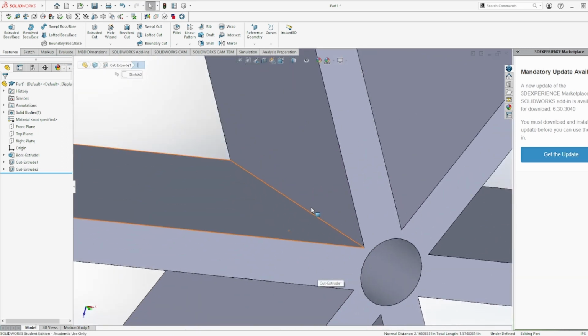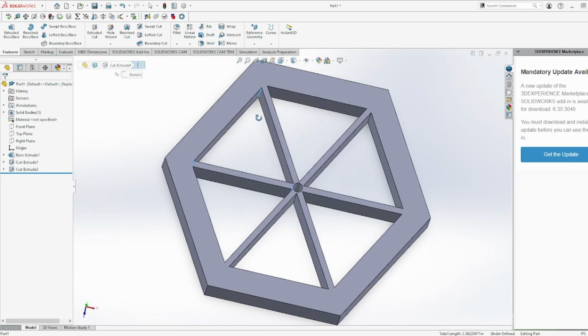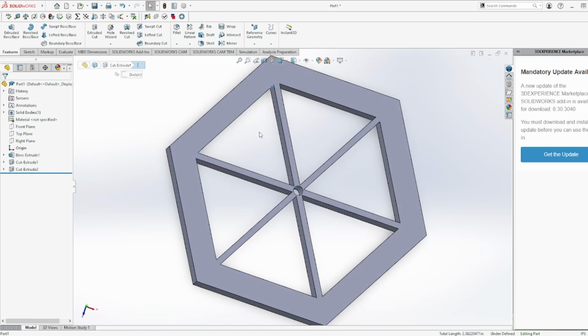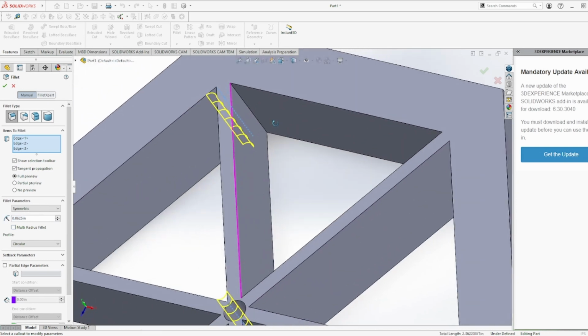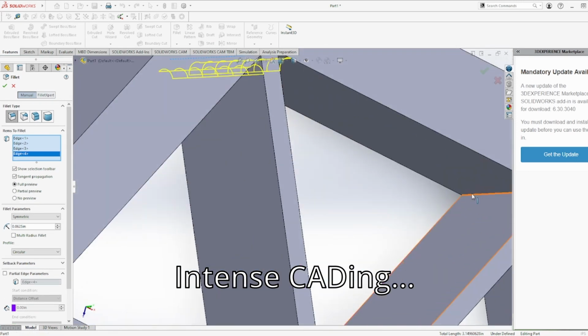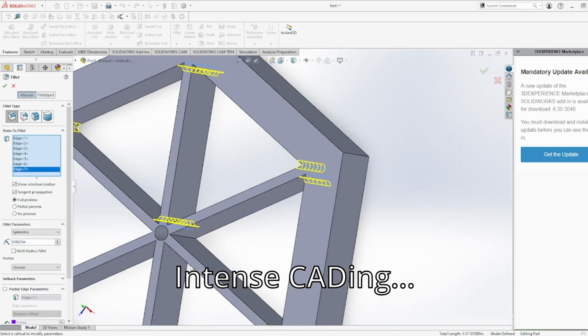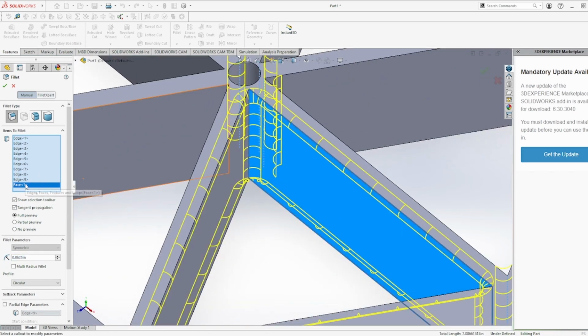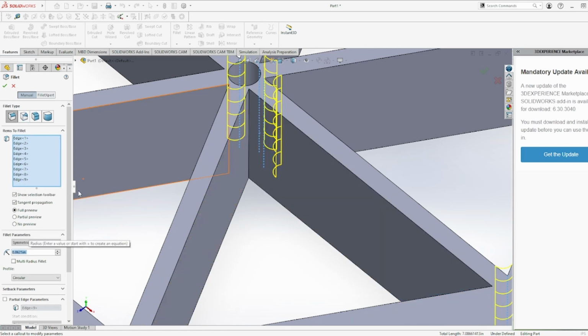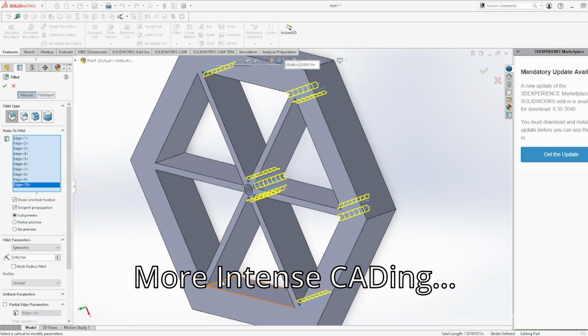So what you want to do is I'm just going to show one, and then we'll do it 6 times later on. So you want to make sure those 3 lines are selected. Come in here. What you want to do is fillet right here. It automatically does the same for you, but instead of 0.1, we're going 0.025. And actually you can add more lines here, so this is probably what I'm going to do here as well. So here, here, here. In case you randomly selected something you're not supposed to select, just click on that and go delete. It just goes away. So good.